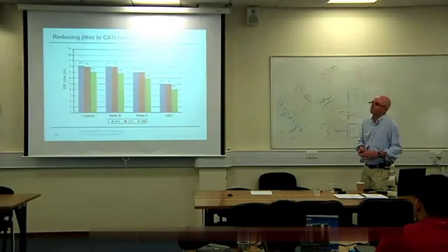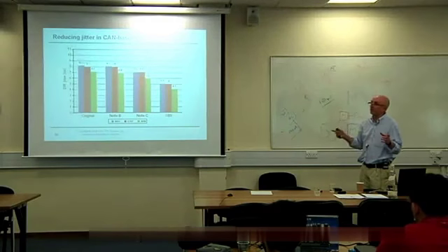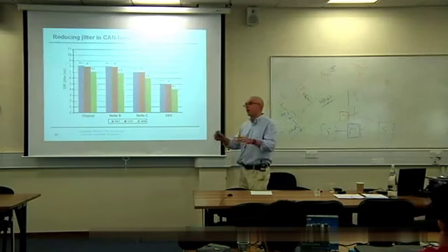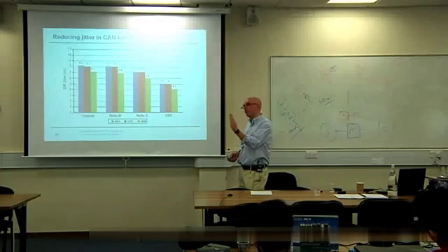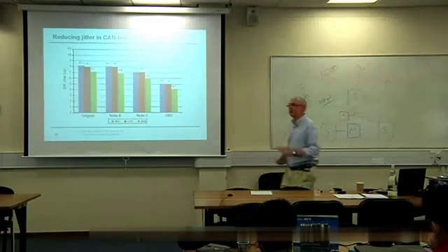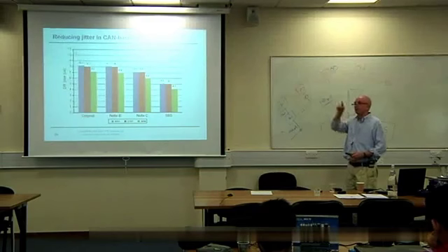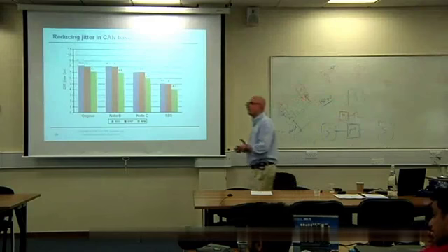Why is the CAN protocol doing the bit stuffing in the first place? Is it for synchronization? It's for synchronization. It has to do it, because otherwise it would send a long stream of zeros and ones, and it would lose the ability to detect. It would gradually drift, and it wouldn't be able to detect whether the signals were 1 or 0. It might end up sampling the signals at the point when it was going between high and low if the clock's drifting. So is the bit stuffing deterministic? Yes.